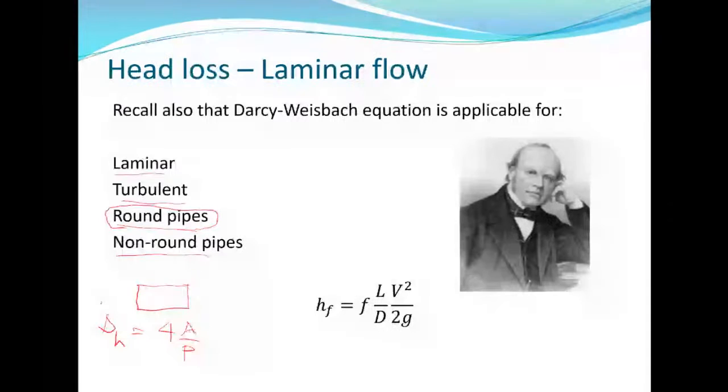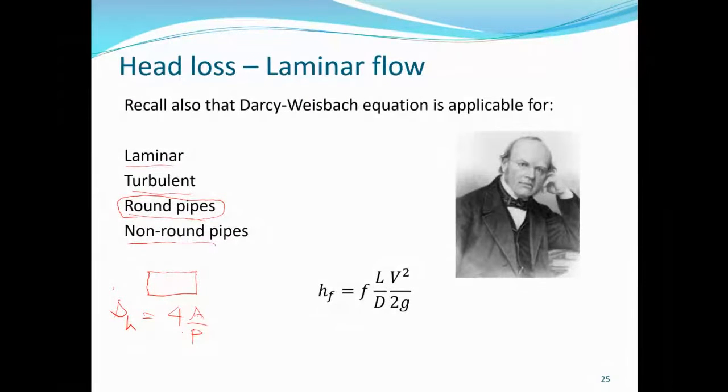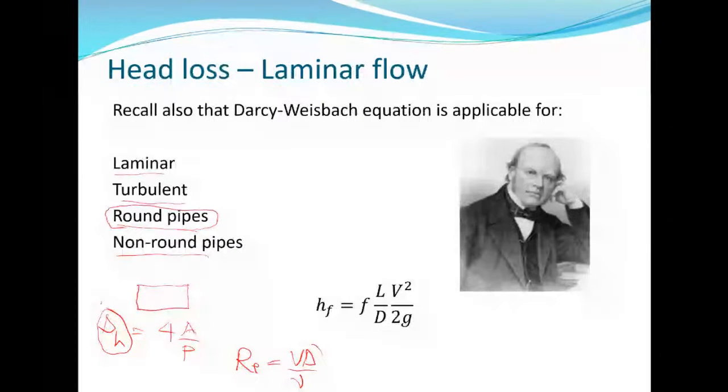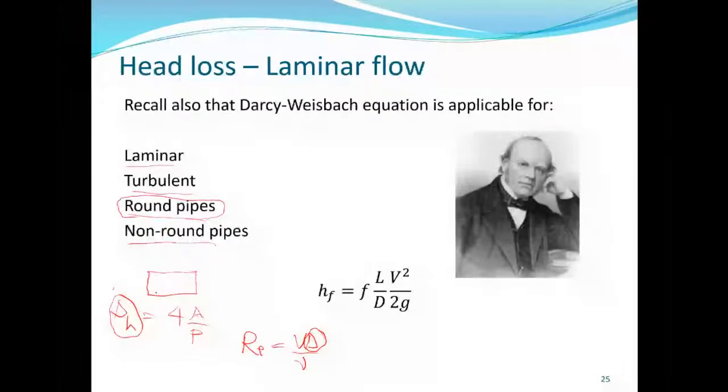Okay, this is surface area over the weighted perimeter. This is how to find the equivalent value for, let's say, when we're using the Reynolds number VD over mu. If it is non-circular, you use this. You find the area of the shape over the weighted perimeter.